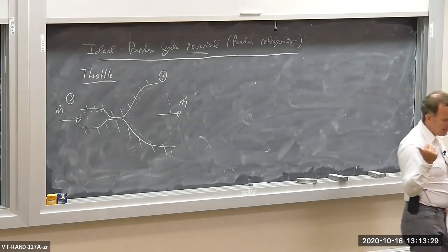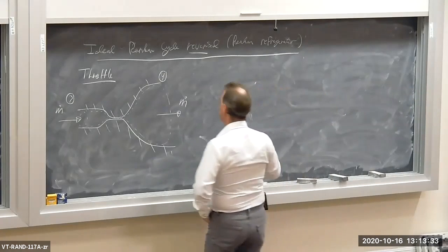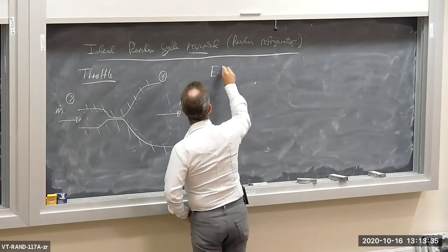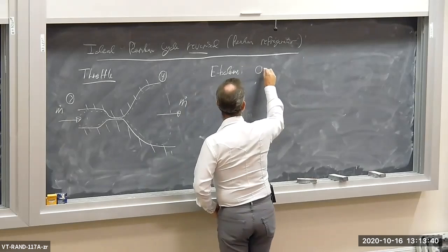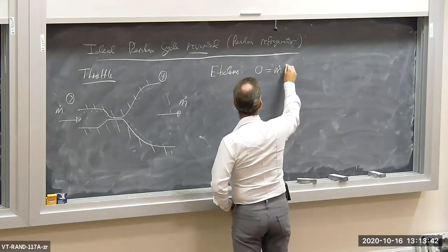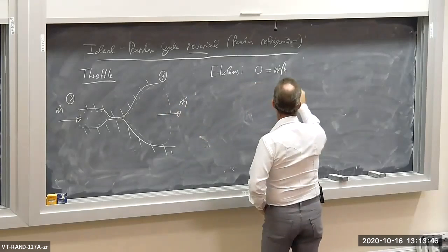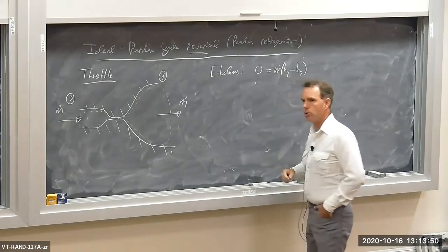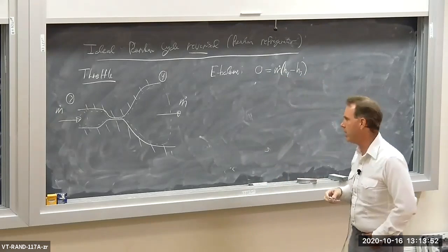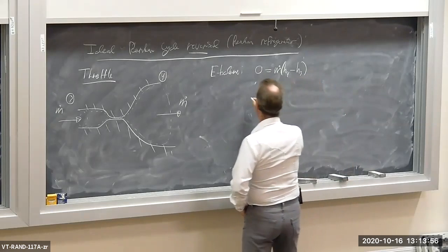If we neglect kinetic and potential energy changes, simple application of the energy balance gives 0 is equal to m dot times h out minus h in, which is h3. The m dots will be the same going in and out. In other words, this is an isenthalpic device.